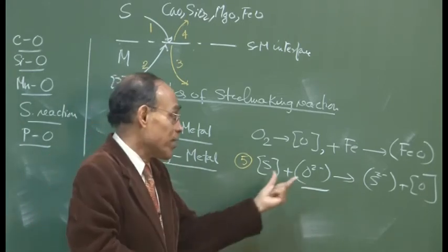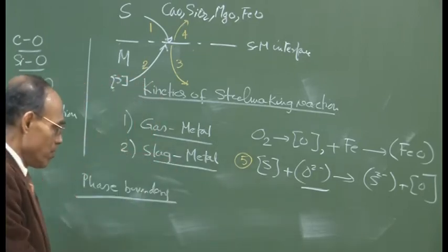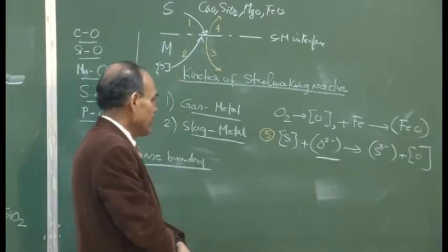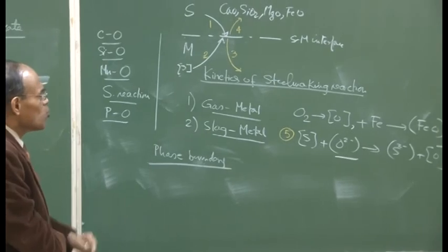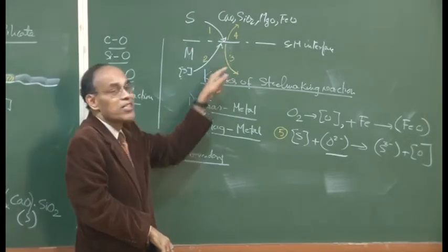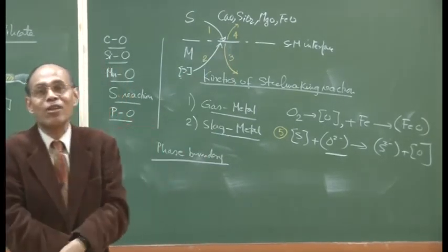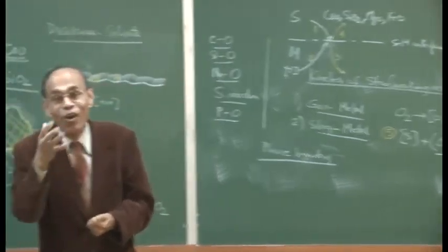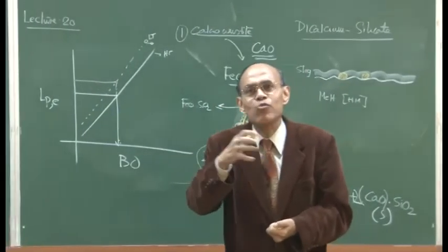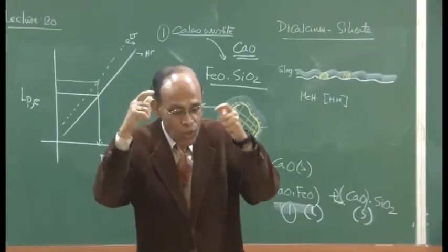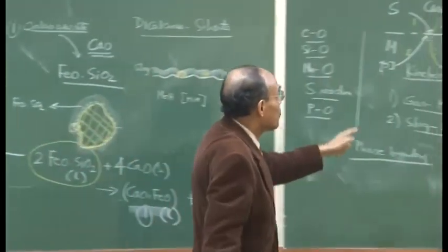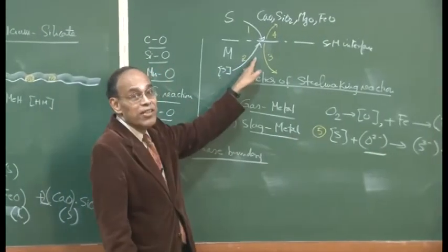There are exceptions of course, when the rate of the chemical reaction may not be that fast, particularly when complexes form or surfaces are blocked by poisoning elements and so on. So, as a thumb rule, under steel making conditions, these mass transfer steps tend to be slow in comparison to the chemical reaction steps, and that is why we have been saying all the time that we need stirring. I have made that statement categorically, that the open hearth process took such a long time for refining, because in the conventional open hearth process there was no good agitation. If chemical reactions are not rate limiting, mass transfer determines the rate of the process.